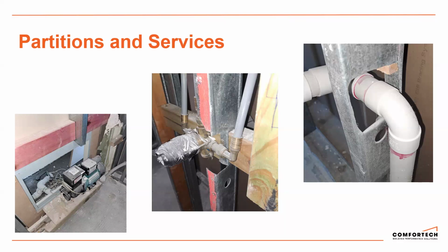Middle one there, another example of where a shower rose is coming out. They've cut 3/4 of that stud out. So, okay, how do we remedy it? Either we put another steel stud in there, or we basically create an opening like a lintel. But again, we need to have these conversations so that it's not left to someone to try and come and fix it after someone's gone.